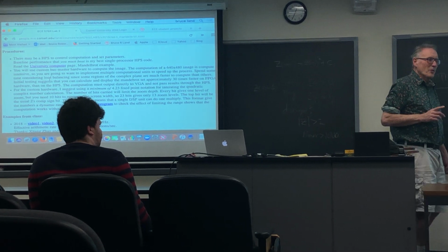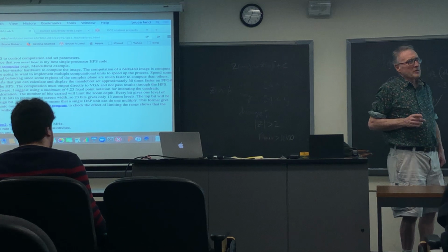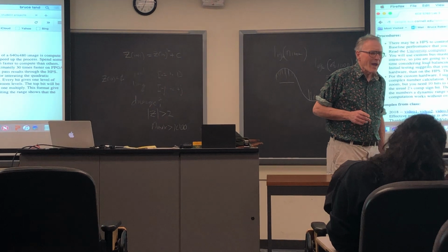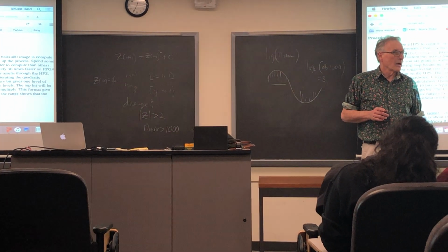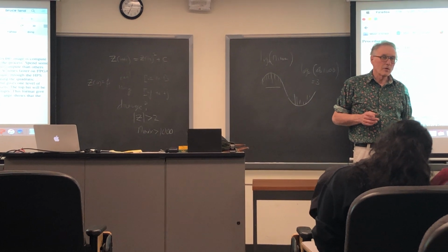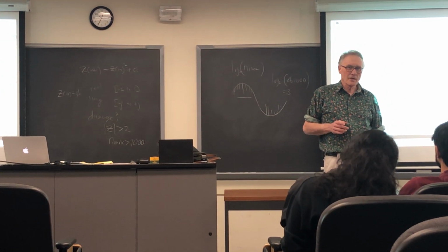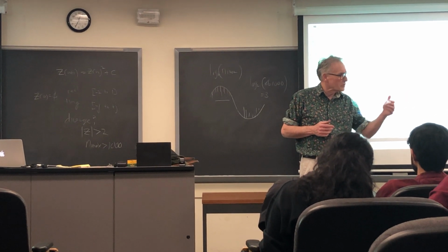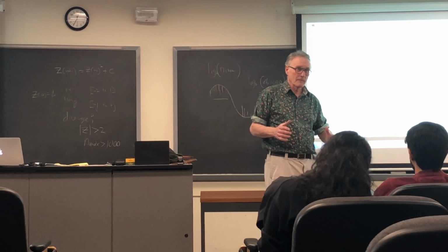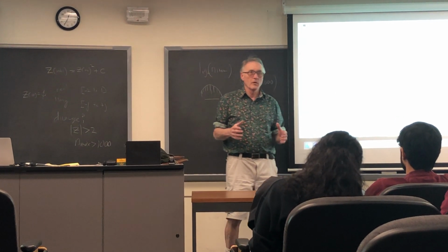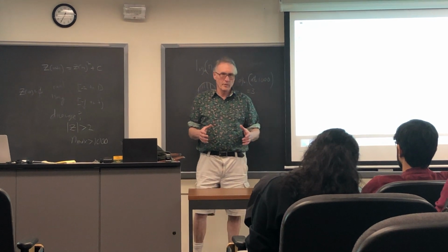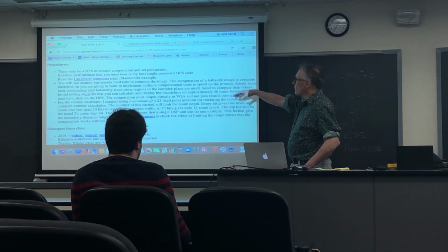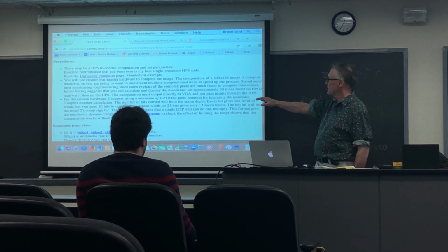Now I'm going to talk about different ways of writing to the VGA, some of which are faster than others. The fastest one I know of requires that you throw away the video subsystem on QSys and write your own. And that sounds daunting, but in fact is fairly straightforward, because you can strip down all the functions you don't actually need for this very specific thing. And one of the students about 3 or 4 years ago did that and put the code up. So there are various ways of writing to the screen, but we'll talk about some of those as the lectures go on.